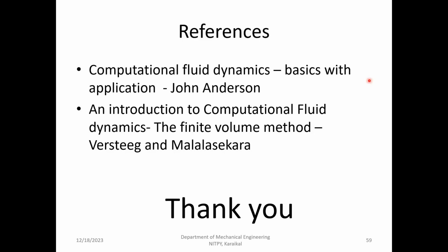And that also must go to Fluent. If you are going with the academic version of Fluent, we have another problem with 5 lakh cells. We cannot go beyond that, because after 5 lakh cells, it will say the mesh is not compatible with the solver. So then we have to come back. And one more thing we can do, depending on the problem, is try some modifications in the geometry itself. Whether you have to go for a really 3-dimensional problem, or whether we can go with an axisymmetric model, or a 2D analysis, those kinds of things we can look into.